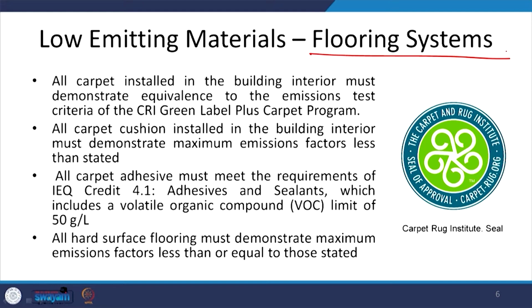However, in the European context or in the Western context, where it is coming from a cold climate, the carpets are essential, and carpets, because of the adhesives which are used, because of the sealants which are used along with the carpets, are associated with very high VOC. So, in case we are going for the flooring system where carpets are being installed, we have to take utmost care of what the adhesives and sealants being used along with the carpets are.